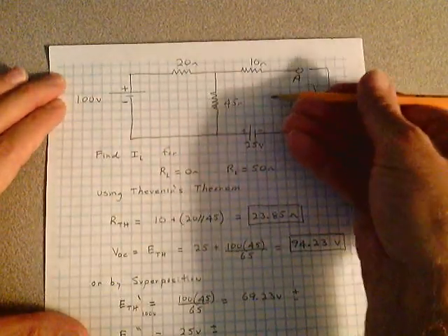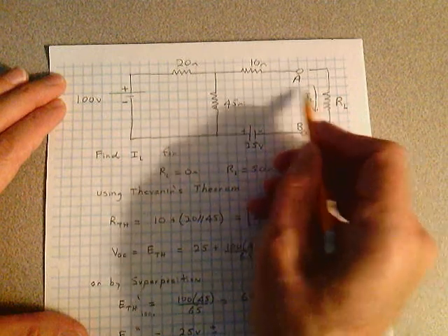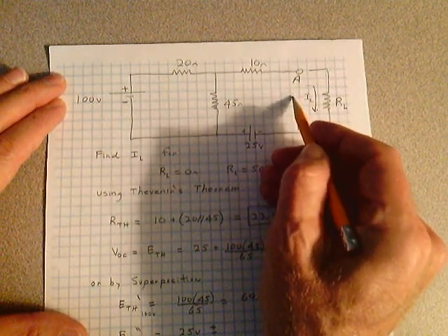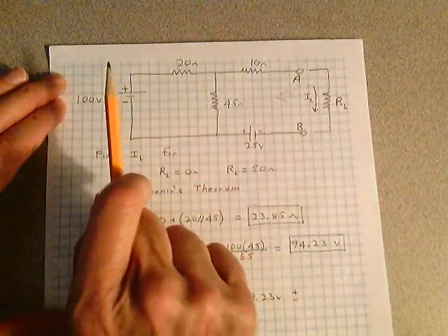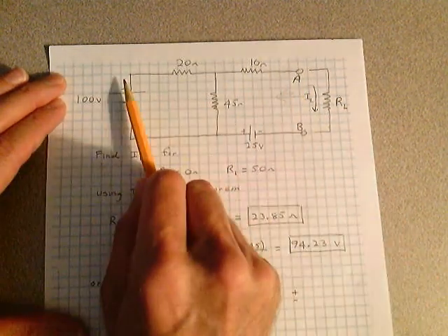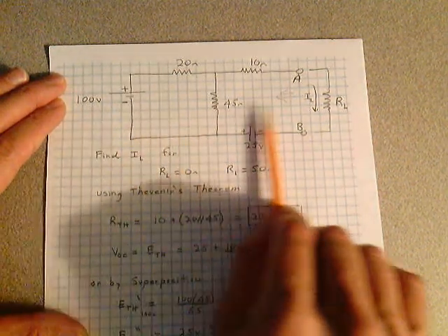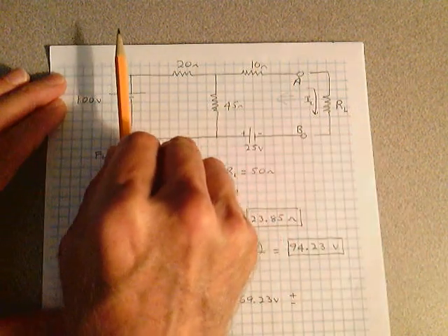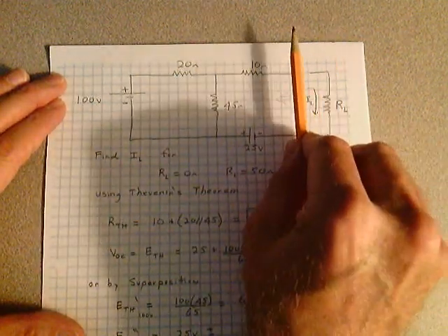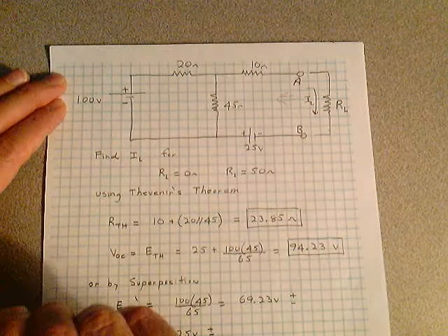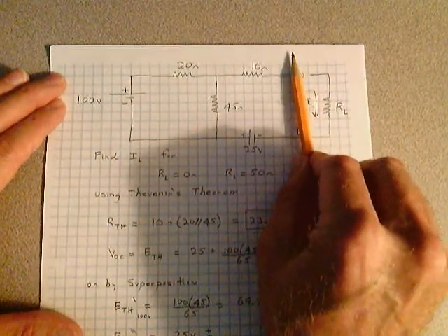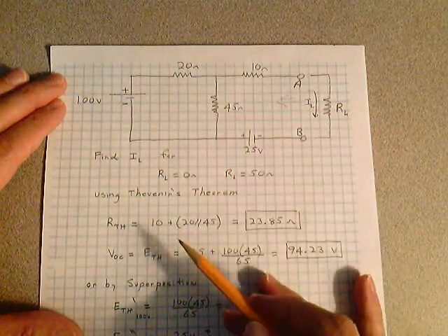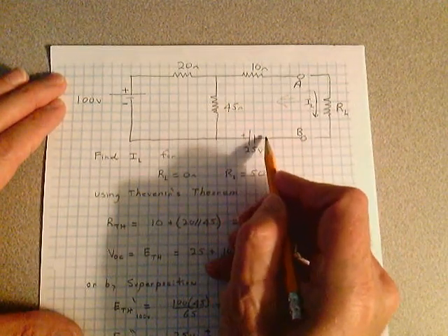Well, I'm going to look back in here. I'm going to look in from this end right here, and I'm going to see what resistance this load resistor sees when you remove it, looking back in this direction. I don't care if you start over here or start here looking in. Some students like to start to the left and work to the right, or they like to start here on the right and work to the left. But one thing you have to do is reduce the sources to 0. That's a voltage source, you short it. I'm not going to redraw the circuit. I think you can picture that being shorted.